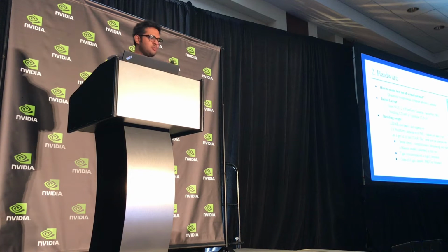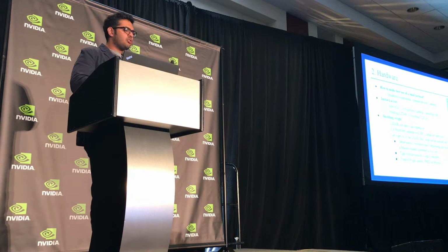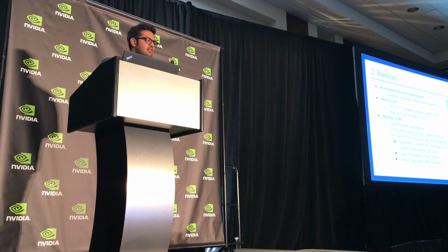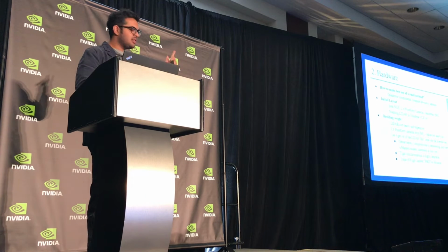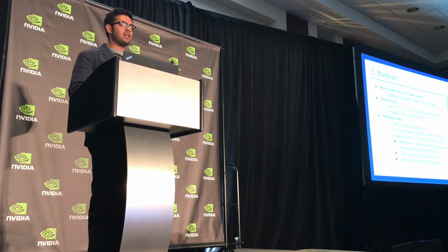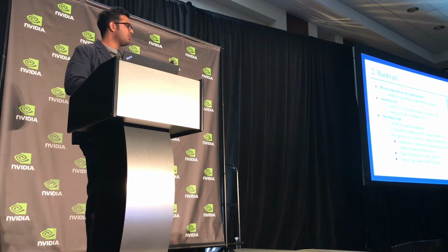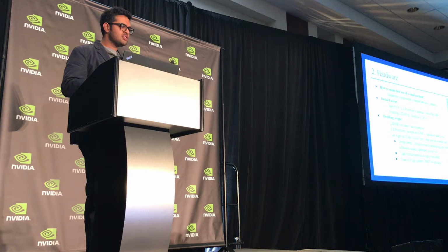So how do we make use of a small payload? Like I said, we were using an Intel NUC, 2 Point Grey cameras for stereo, a VectorNav IMU, and then our first platform had a Velodyne 16-beam laser. We eventually switched to a nodding Hokuyo, as you can see in the top image, but then DARPA said make it even smaller. We need this thing to go through windows and doors.